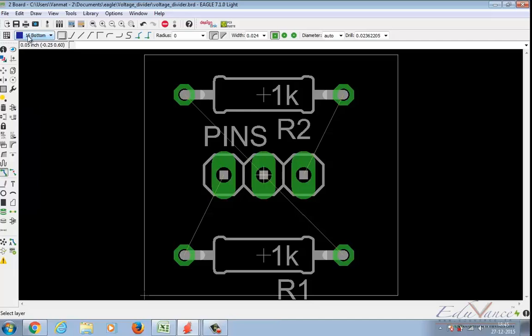Then there is a tab which reads top and bottom. We'll look at that after some time. And then you have multiple options which are angles. You have an obtuse angle, you have a slant line, you have a 90-degree. But these are wire bends. So you shouldn't be working with 90-degree wire bends. You should always be working with an obtuse angled wire bend. So select the wire, select the bend style and start connecting.